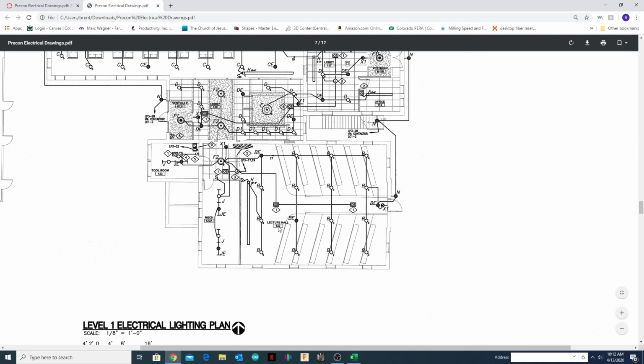We're going to do 122 lecture hall, the 122A mechanical room, and the 123 tool room. The only exception is we're going to go ahead and do this light right here that's on the outside. So basically, we're going to do a quantity takeoff just on this section. We're not going to do the whole building. That's a little too tedious for what we want to do.